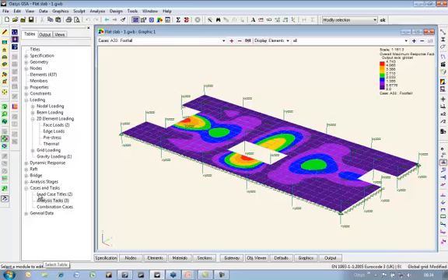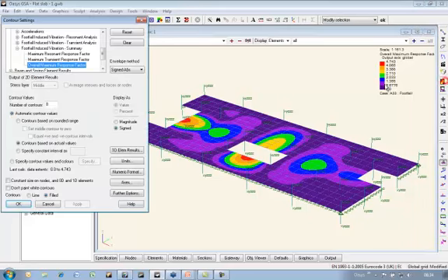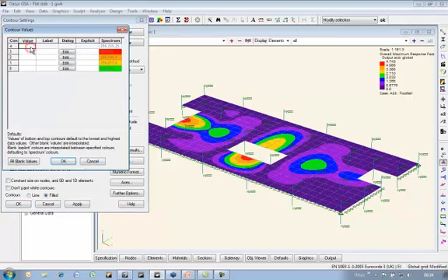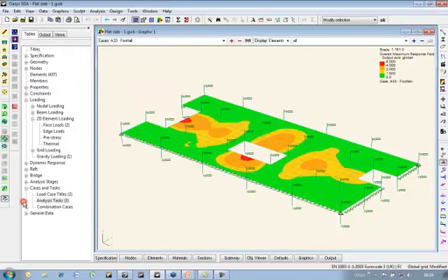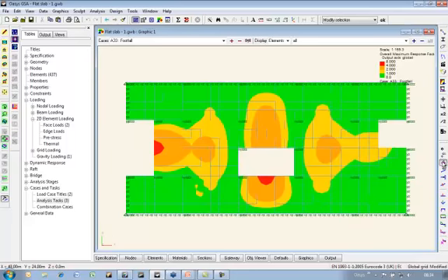And you see in this case we're getting footfall results just under 5, which is much more acceptable, especially for an office. For a high spec office, you'd be looking for results under 4. And if we were to adjust these contours, let me see, if we specify 8, 4, 2, 1, 0, we can see for the high spec office, values anywhere except in the red zone are perfectly acceptable.